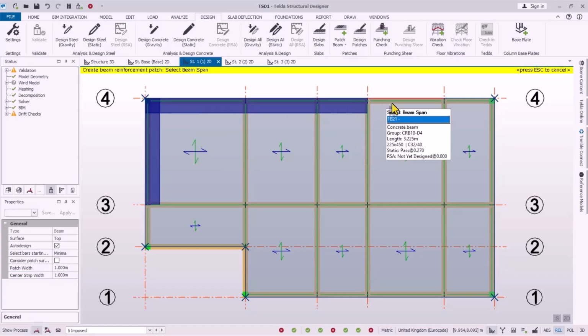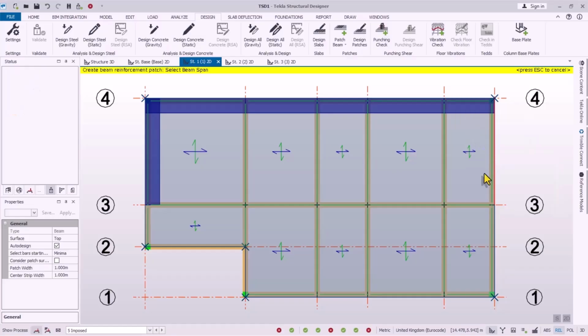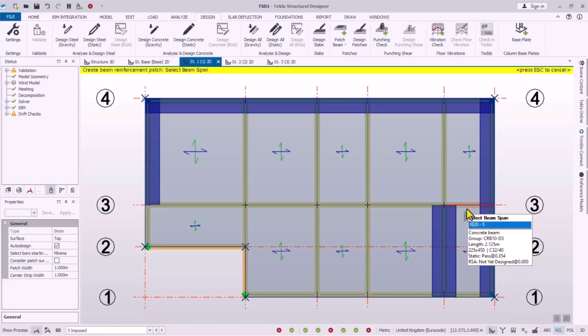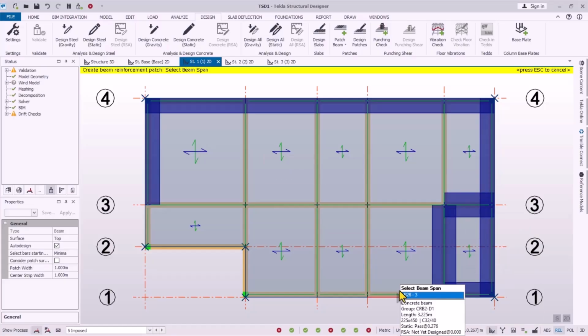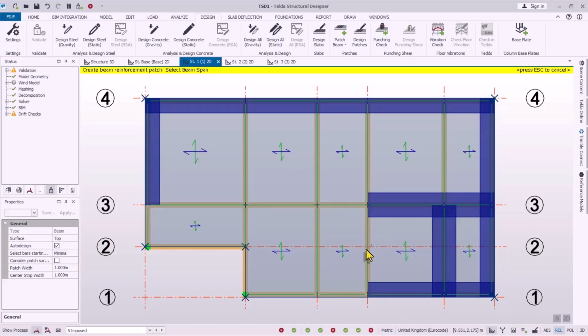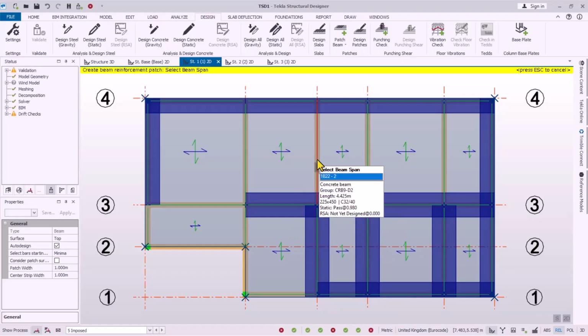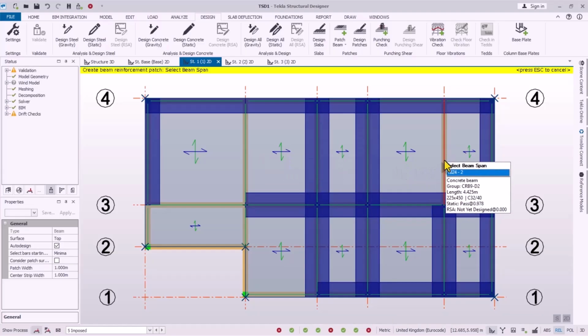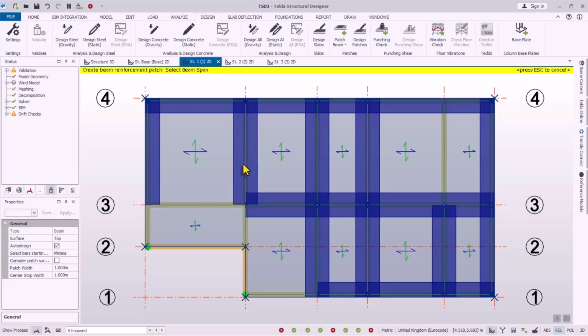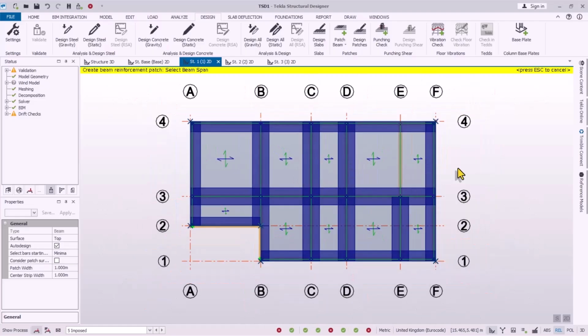So this will serve as my top bars. In applying this, you have to actually be calculative. So I will apply this successfully, just like this. These are my patch. Apply this over here. I wouldn't want to apply it because that provisions is for staircase. I'm not supposed to add this one. You apply the patch just like this. We are good on this floor.